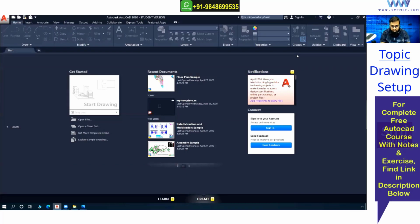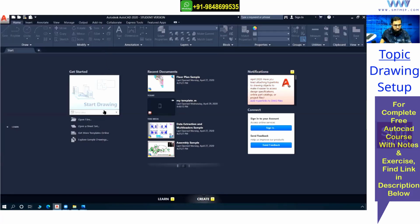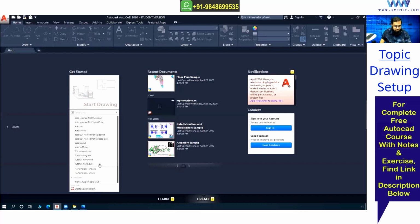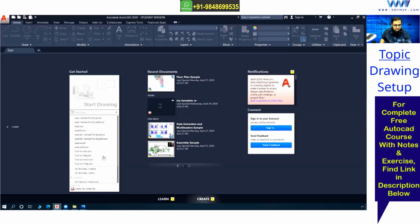Next time, if you want the same settings, same limits, same units, etc., for any project, I can directly use the template in the project. Okay, so how to use the template in the project? Directly go to the application menu and go for New. You see, if you want to select the template from the default, you can directly select from here. In that, my template is not available, which I saved just now, because these are the templates in the default location. So if you want to use the default template, directly select from here, and the project starts from the default template.